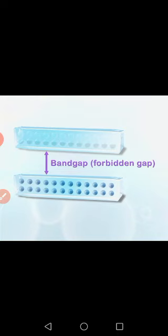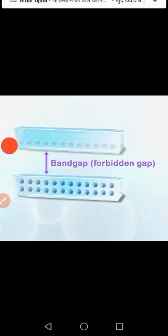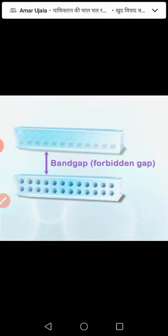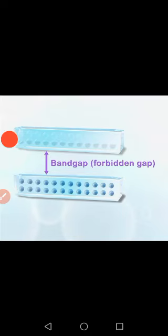Why forbidden gap? Because in this gap no electron is allowed; no electron can be in between these two bands. So if any electron gains sufficient energy to transit, then it goes from the valence band to the conduction band, but it cannot stay in between the valence band and conduction band. So this is the condition.